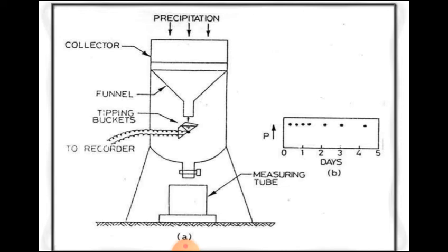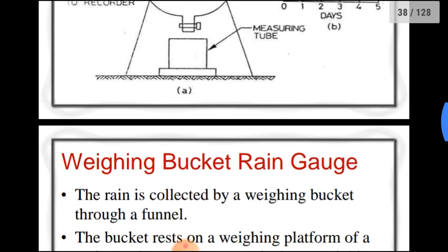So if you have, let's say, 15 gauges in that area, 1 or 2 should be recording rain gauges. Based on the record of that 1 or 2, we can estimate temporal variation of rainfall at the other stations. That is the reason this percentage should be required for recording rain gauges. Once we collect the rainfall data, we should analyze the data. Next, we discuss data analysis.